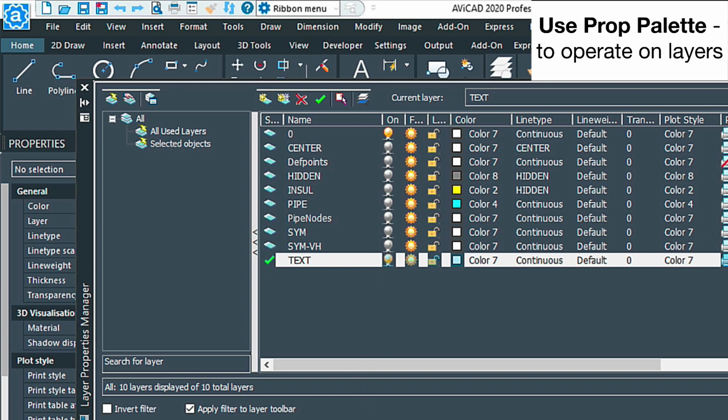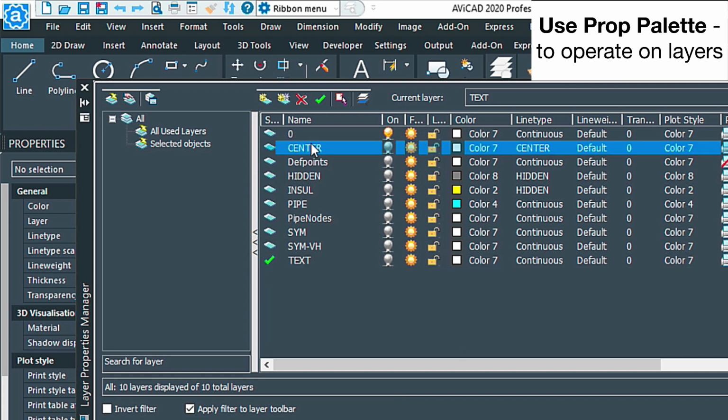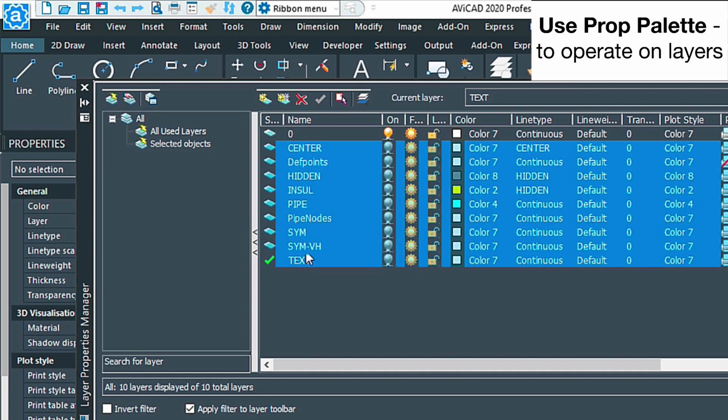There's an easy way to actually turn all those layers back on through this menu here. So if you select the first layer, the one that's turned off, see all of them that are turned off right now, and then the last layer, and hold your shift key down at the same time, then you can just turn them all off and all on as you need.